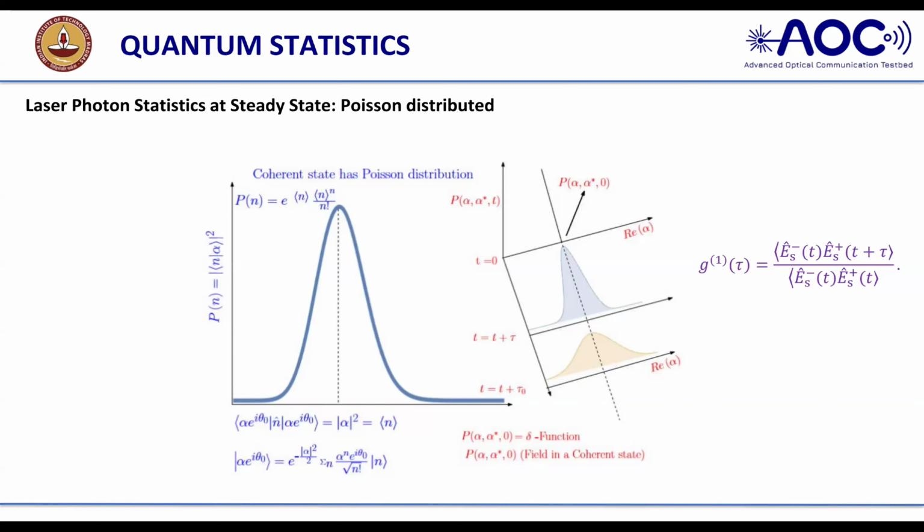But in our case, from the laser, it has phase noise, it has intensity noise, right? And then how is it happening? If you see that at time t equal to tau, you will start getting Gaussian. Then it goes to the optical channel, and it starts spreading more with respect to time, right? And how can you do this analysis? By the degree of coherence. If you calculate here t plus tau, take the autocorrelation, and then take the Fourier transform, you will observe this picture that we have written here, t plus tau.